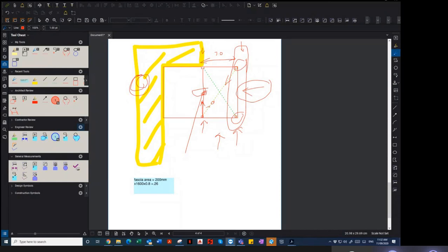Toolkit actually has the facility to choose the type of loading to check, compression load. I've done a quick check, and the capacity with the load is at 0.05. So your timber rafter in this instance works quite well.